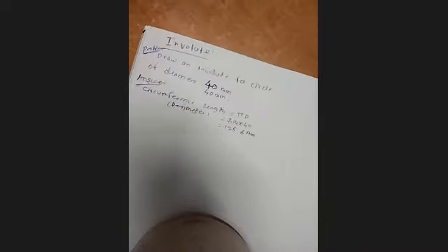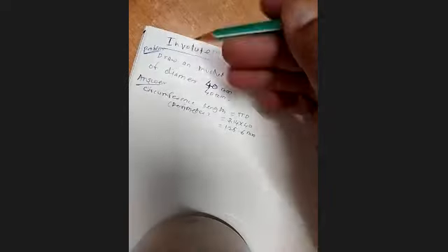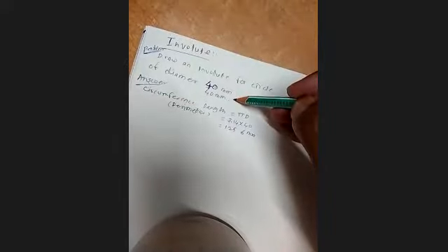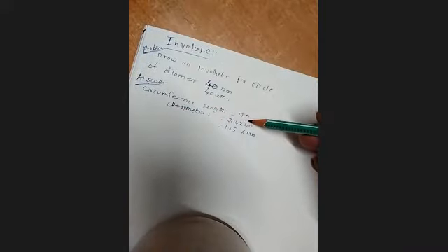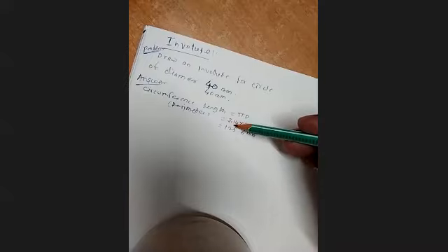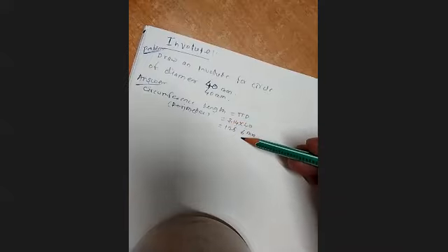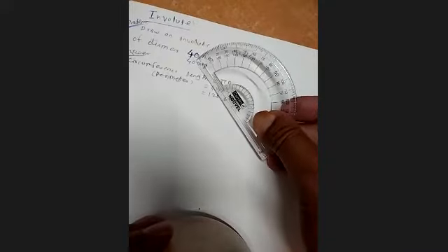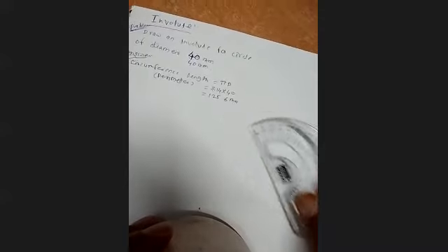So for that, this is the problem statement. Draw an involute for a circle of diameter 40 millimeter. Then you have to calculate the perimeter, or the circumferential length, by using the formula pi d, that is 3.14 into 40. So we will get 125.6. Okay, so let's start with the actual graphical answer for this. I hope you remember this 40 millimeter diameter of the circle. So pi d, with calculation you will be getting this.